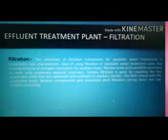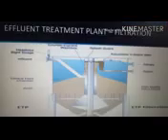In the filtration picture, there is clearly a counter-current wash box, splash guard, head loss side guard, influent central feed chamber, and air lift. An adjustable V-notch weir, filtrate and reject, and high quality silica media are also available in ETP filtration. These granular media filtration systems remove fine non-settleable material.